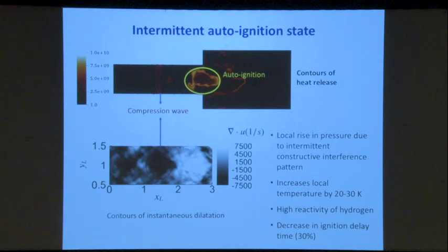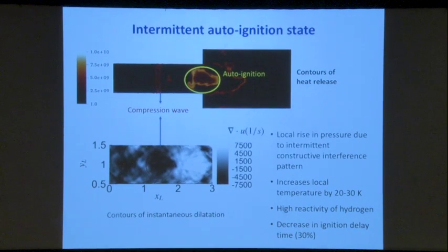Well, first I should say, when you have a big body of autoignition happening in the combustion chamber, it gives rise to an increase in the pressure that generates pressure waves that propagate both upstream and downstream of that ignition, that triangular ignition region in the combustion chamber. And the waves that propagate downstream are fine. They leave the domain or the combustion chamber.